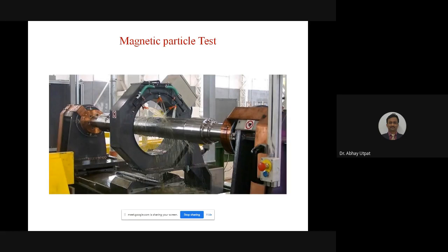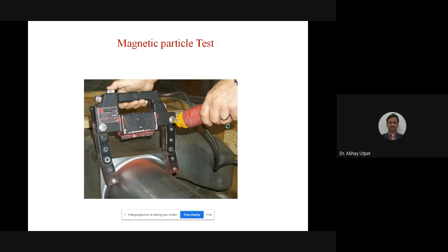See in the actual photograph, it is clean, and then the magnetic field is applied for checking the presence of crack. So I was telling this. This is called a magnetic yoke. This is one end, this is another end. So from here to here, directly magnetic field is there. I will draw the lines. These are the lines of magnetic field.